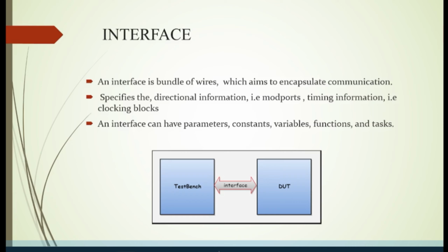Generally, those values which you want to put from the test bench to the DUT, you will introduce all those variables within your interface. That is the simple version. Again, within this interface you will have the virtual interface concept. You will see that also in depth once you get deep into the topic, right?